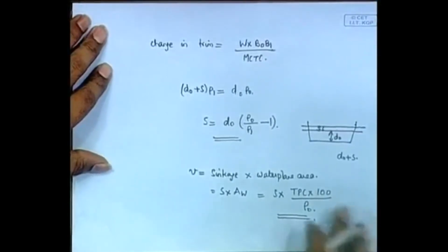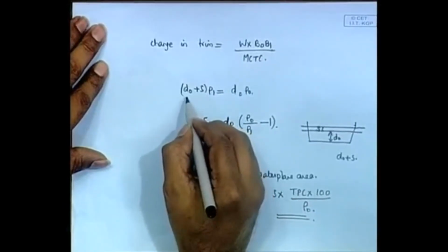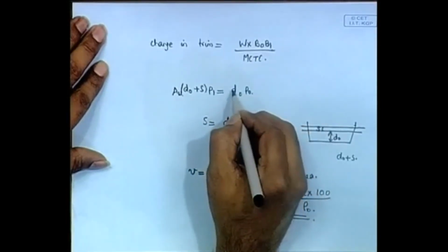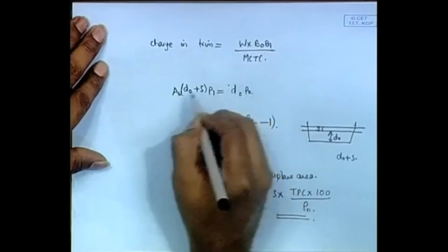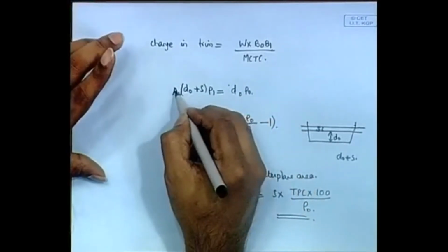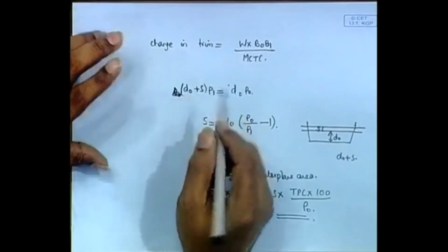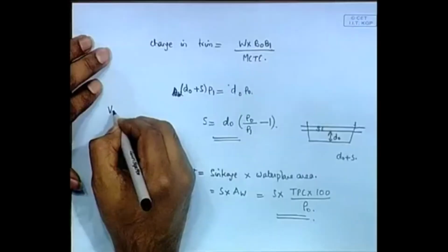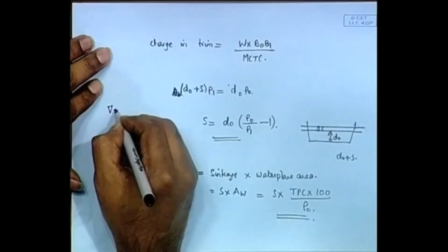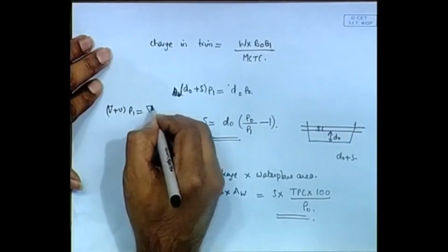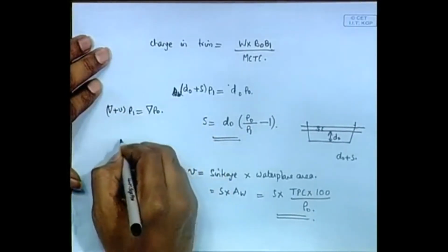Now this expression, see, there is an AW also here. It's not exactly this, this should be AW plus the new AW, but we are assuming it to be almost same, because water plane area doesn't change much because of change in draft of probably 10 centimeter or something. It doesn't make any difference. The real expression is like this.